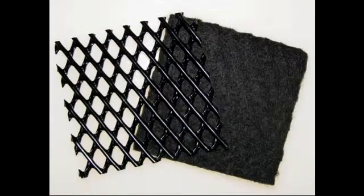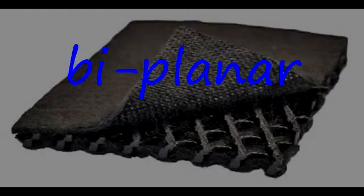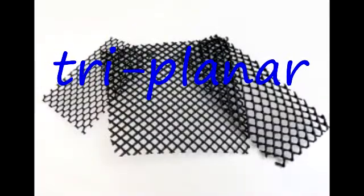Geonets. A geonet is a geosynthetic material consisting of integrally connected parallel sets of ribs overlying similar sets at various angles for in-plane drainage of liquids or gases. Geonets are made of stacked criss-crossing polymer strands that provide in-plane drainage. 2 layers of strands are called biplanar, while 3 layers are called triplanar.